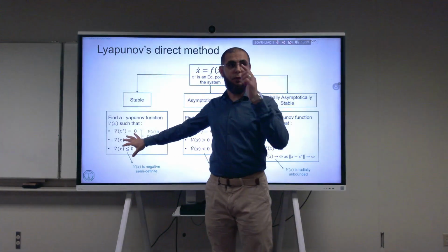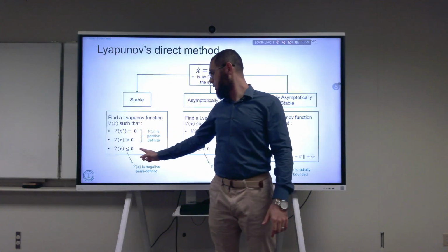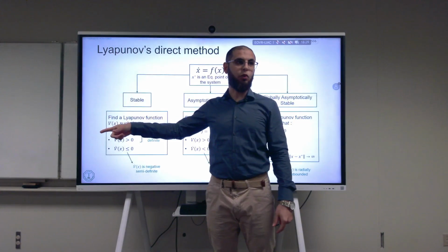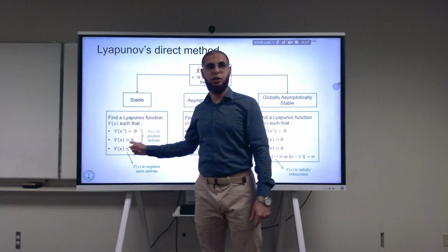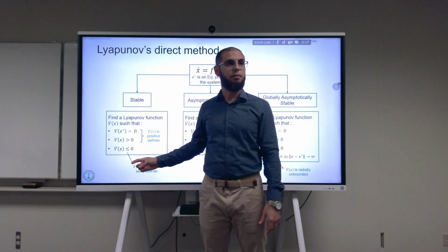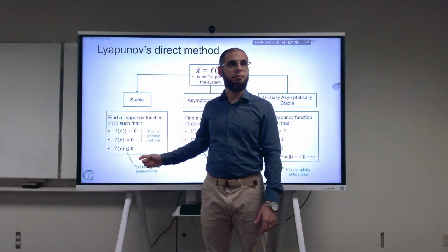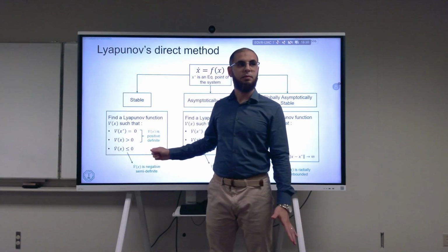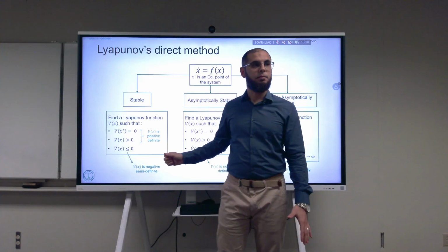So you find a Lyapunov function, and you cannot show that it's actually stable. And next room, I find another Lyapunov function and I show it's stable. Who's true? The stable one. Because you need only one to prove that it is stable. Exactly. But we are talking about the methods of Lyapunov, not Lyapunov's theorem. I'm talking about the original Lyapunov theorem. What's the original theorem? It only relates to the nature of the equilibrium point itself.